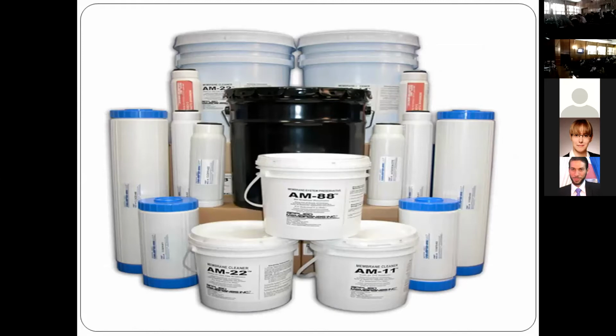The membrane life decreases and the oxidative damage increases with time, so we need to replace the unit every month, much earlier than expected. The companies supplying the membrane say it lasts 5 years, but they found it does not complete 1 year in some wells and locations.